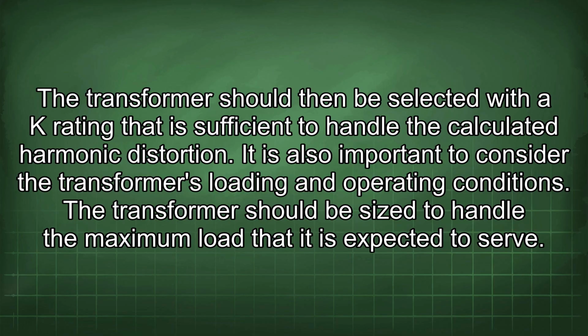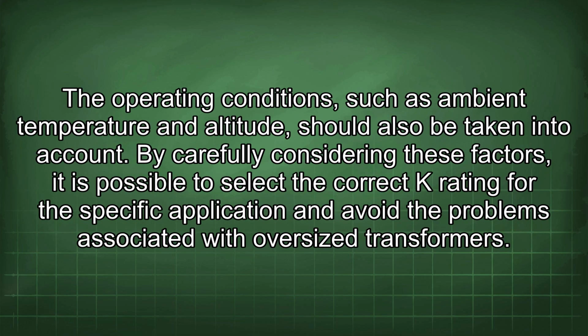It is also important to consider the transformer's loading and operating conditions. The transformer should be sized to handle the maximum load that it is expected to serve. The operating conditions, such as ambient temperature and altitude, should also be taken into account. By carefully considering these factors, it is possible to select the correct K rating for the specific application and avoid the problems associated with oversized transformers.